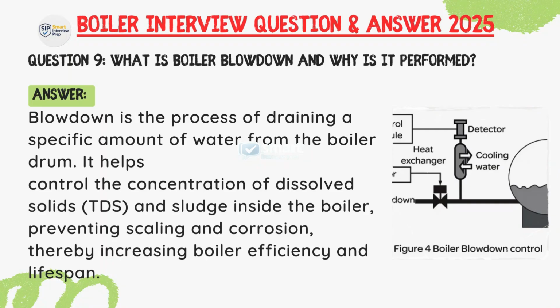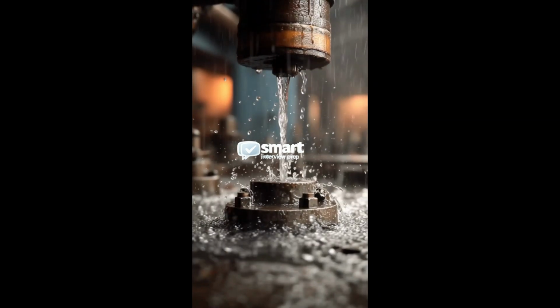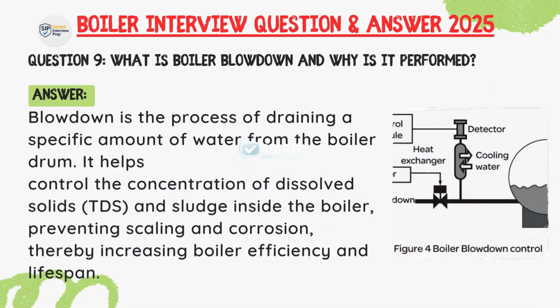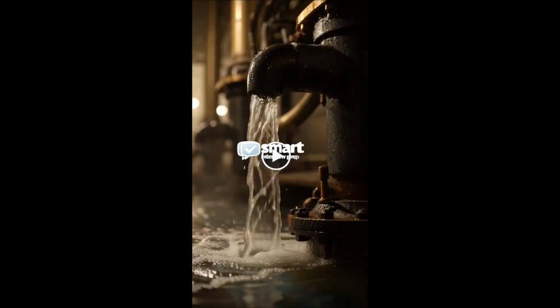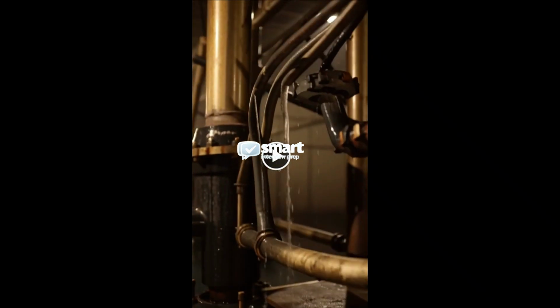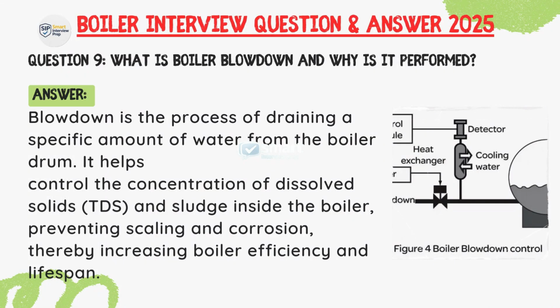Question: what is boiler blowdown and why is it performed? Answer: blowdown is the process of draining a specific amount of water from the boiler drum. It helps control the concentration of dissolved solids like TDS and sludge inside the boiler, preventing scaling and corrosion, thereby increasing boiler efficiency and lifespan.